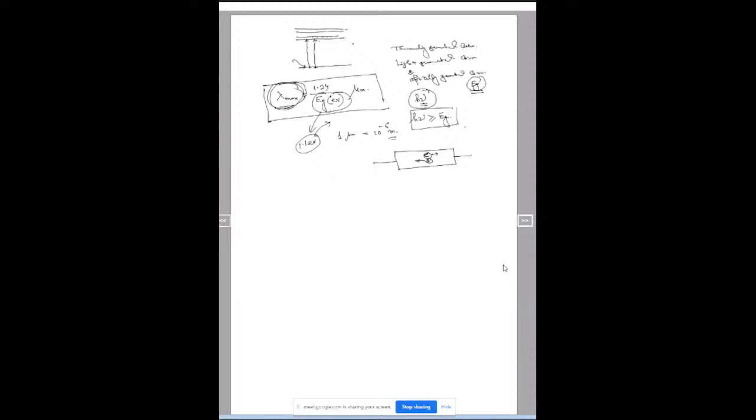When the semiconductor is in the dark condition, some electron holes are present here. Now when you shine light on this material, there will be additional electron holes optically generated here. So because of the larger number of carriers, the conductivity of this material will change.